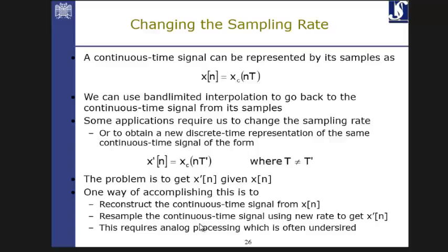Now, the idea of changing the sample rate. That's really necessary in practical experiments, to have the ability to change the sampling rates. For example, someone gives you a database that contains a signal which is already sampled at 44.1 kilohertz, and the entire process that you're doing is with 16 kilohertz. You want to know what happens when everything is in 16 kilohertz, or at least you have some training data or test data which is in 16 kilohertz.